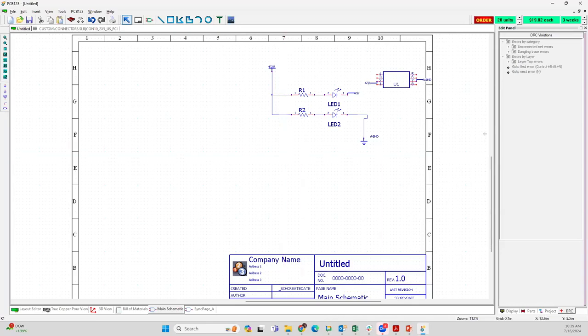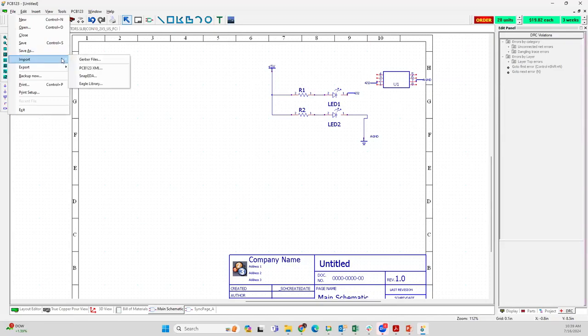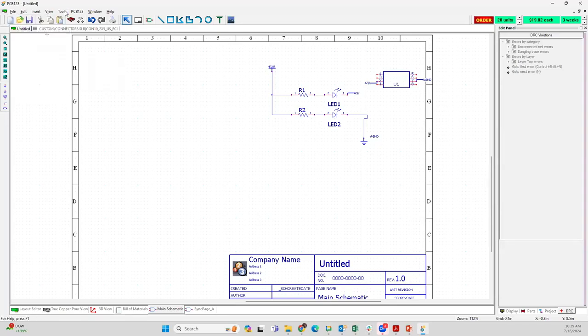If you want to edit a schematic, you have to output a net list and then import that net list using the file import, PCB tools, net list, prepare, update, design, and somewhere in there there's a way to import the net list. I haven't done that for years.